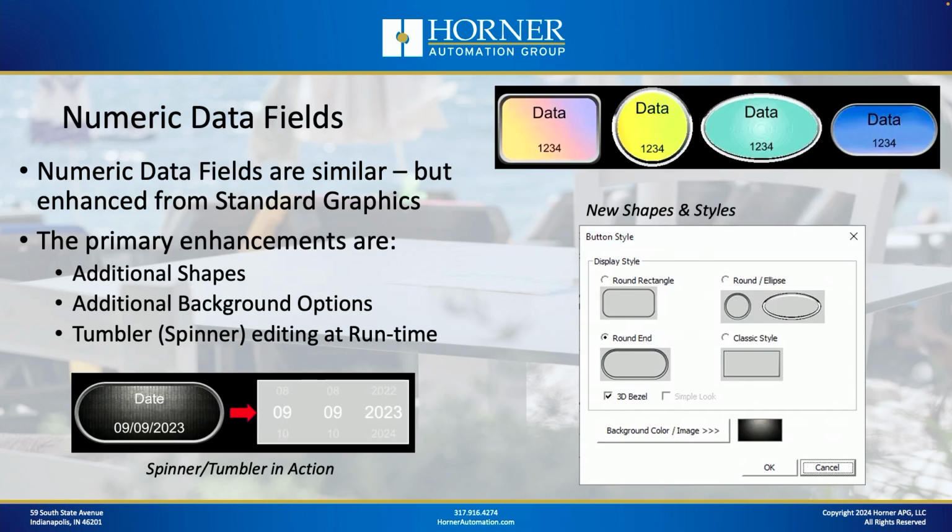All right, let's start with numeric data fields. Now, a numeric data field is one of the basic building blocks of any industrial operator interface application. It's the way you display variable data on the screen to show it to the operator. You also use these objects, of course, so that operators can change set points and that sort of thing for variables where you want the operator to have that capability.